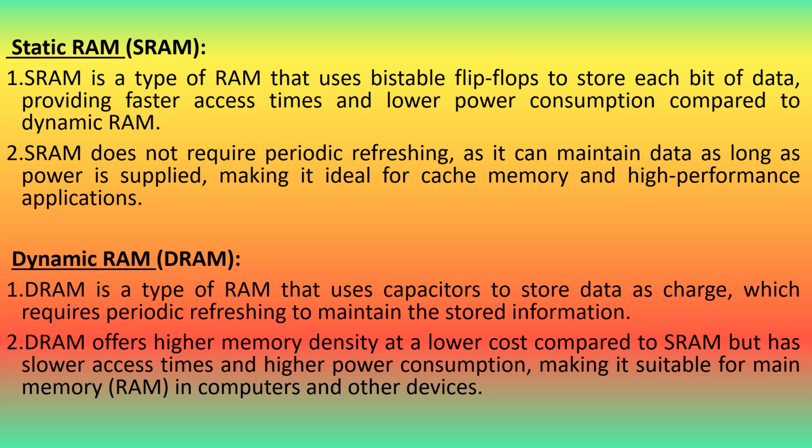Static RAM, SRAM. SRAM is a type of RAM that uses bistable flip-flops to store each bit of data, providing faster access times and lower power consumption compared to dynamic RAM. SRAM does not require periodic refreshing, as it can maintain data as long as power is supplied, making it ideal for cache memory and high-performance applications.